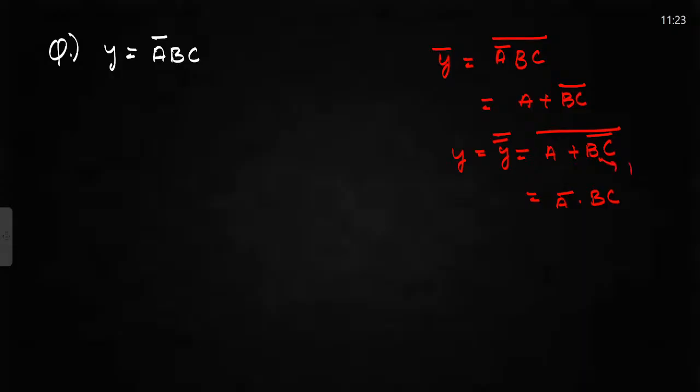For this one, this is 1, and for OR you require how many? For OR operations we will require BC and 3. So for OR you require 3, right? So 3 plus 1 is 4. So here we are requiring 4, and you need another extra complement. So in total you require 5 2 input NAND gates.